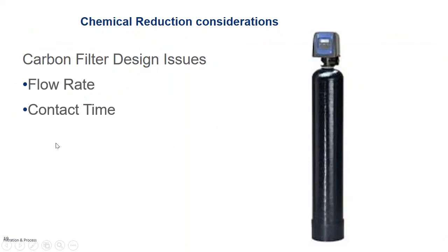We talked about that earlier. You have surface area and depth. How wide of an area do we spread our water over to get contact, and how deep of a media bed do we need to get that contact time? Both of these are critical factors in generating your appropriate contact time.